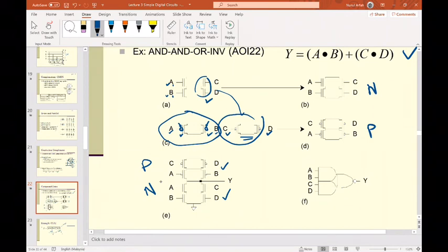Okay, and like I said, this is the drain. This is source. This is the drain. This is a source. This is a drain for NMOS. This is for PMOS. So PMOS here, you have the source here, and the drain should be connected all to output. And the source for NMOS should be connected to ground. Okay, so source for PMOS should be connected to the higher polarity or the VDD. Usually we don't put VDD, just put it like this.